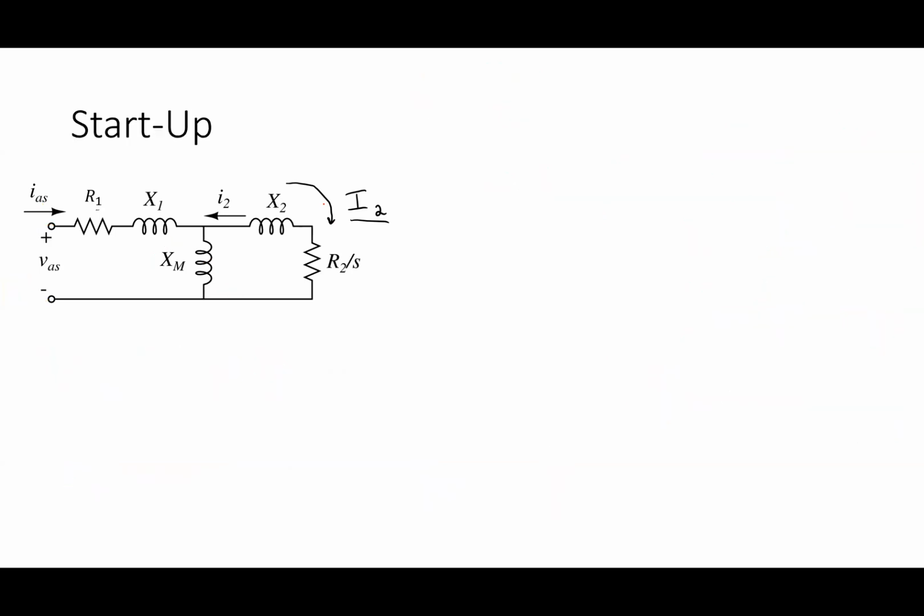All right, now intuitively, what's going to happen here? Let's think about this: startup and full load. I want to skip the full load first. Actually, I want to say it this way: at no load, full speed. Okay, at no load, full speed. How much current do I have in the rotor at that point?